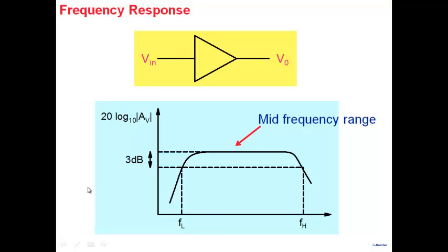Let's come back now. We have seen input resistance and output resistance. And we have also looked at output current driving capability. Let's next look at the time response, or another way of saying it, the frequency response. These two are complementary in some sense. So every amplifier will have a frequency response. Here I've plotted the voltage gain, 20 log 10 AV. Let's say this is AV0, open circuit gain, as a function of frequency.